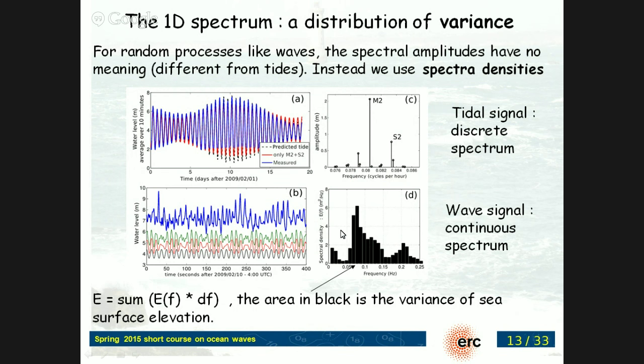So this is an example of a wave spectrum. As I said, I should have put some error bars on this, which maybe would be like a factor 2, plus or minus, because this is only over something like 20 minutes. If you can average the spectrum over a full day, the error bar maybe will be plus minus 10%. But usually during a day, the sea state has changed, especially in a tidal environment. You get low tide and high tide, you get different waves. So you always have some uncertainty in your spectra, and you have to live with that.